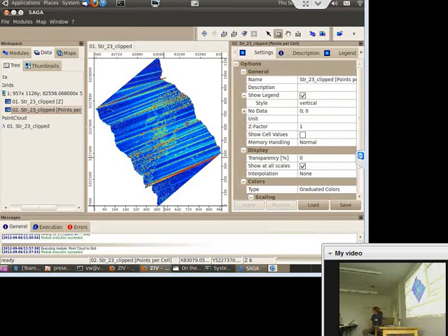The cell size one data were based on local projection, no? Because they were not projected. The projection of point clouds is based on a local system of the aircraft, no? Yeah, first of all it was, but the data then was projected. No, it has been projected. So the one refers to 1 meter, the cell size resolution of this grid. Yeah, we have a resolution of 1 meter now. And how does it make the average of the 10 or 20 points that were in the cell? In this grid, it's just the number of points. In the other one, it took the highest point. Yeah, the highest point.